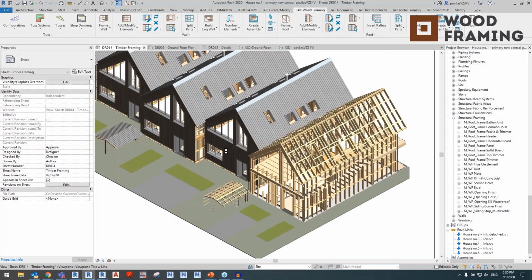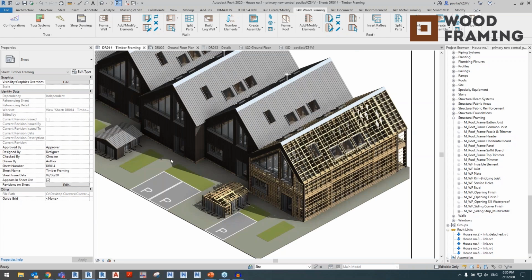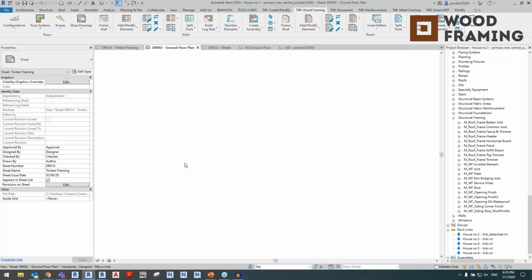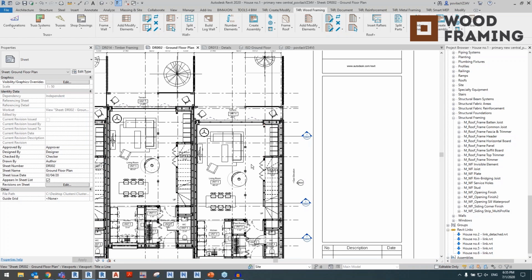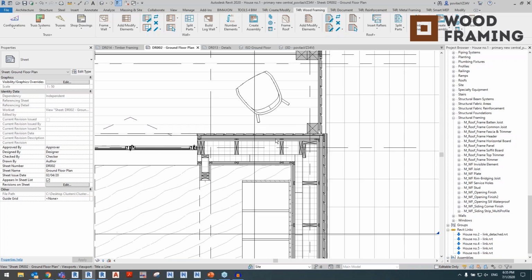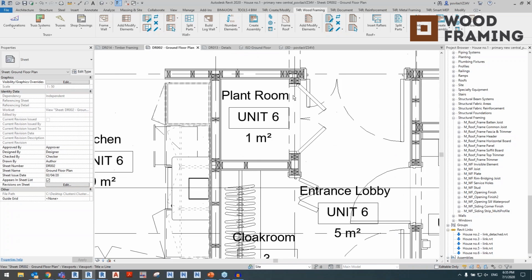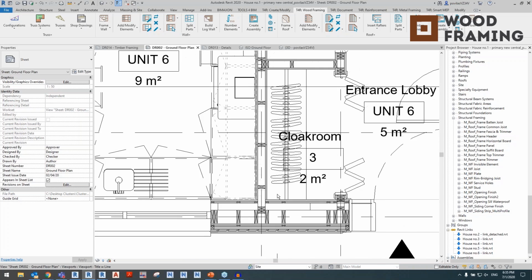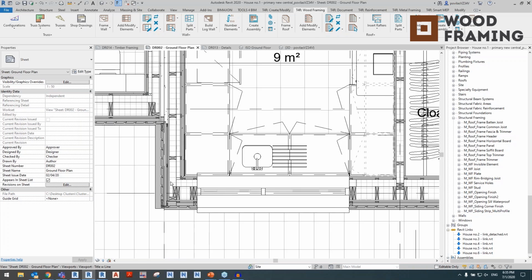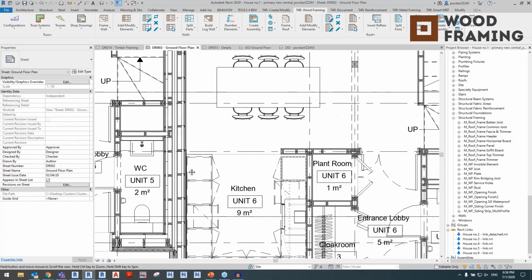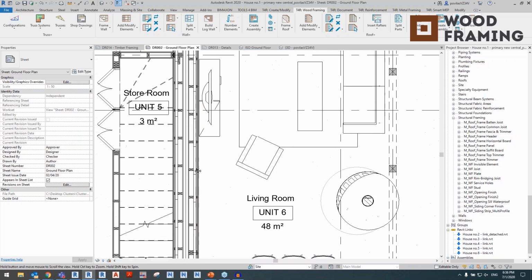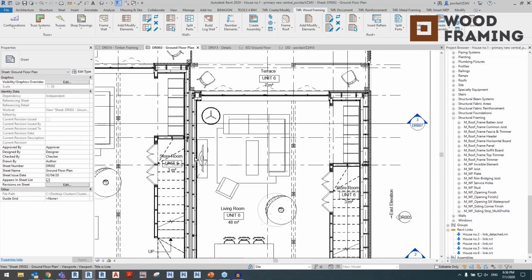You can also add roofing, siding, wall siding, like I have shown you. And if we go to the ground floor plan, we can see those elements have been distributed according to my configurations. Okay, and the junctions have been resolved. Even if I had some issues, I was able to resolve those junctions simply by manipulating configurations.